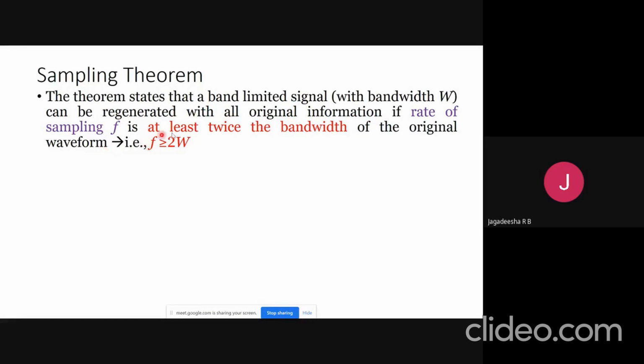That is the condition. So how frequently you need to cut the continuous time signal to make it discrete, or while sampling, is given by this key relationship. The sampling frequency, how frequently you need to sample, depends on the maximum frequency of the signal you want to sample.